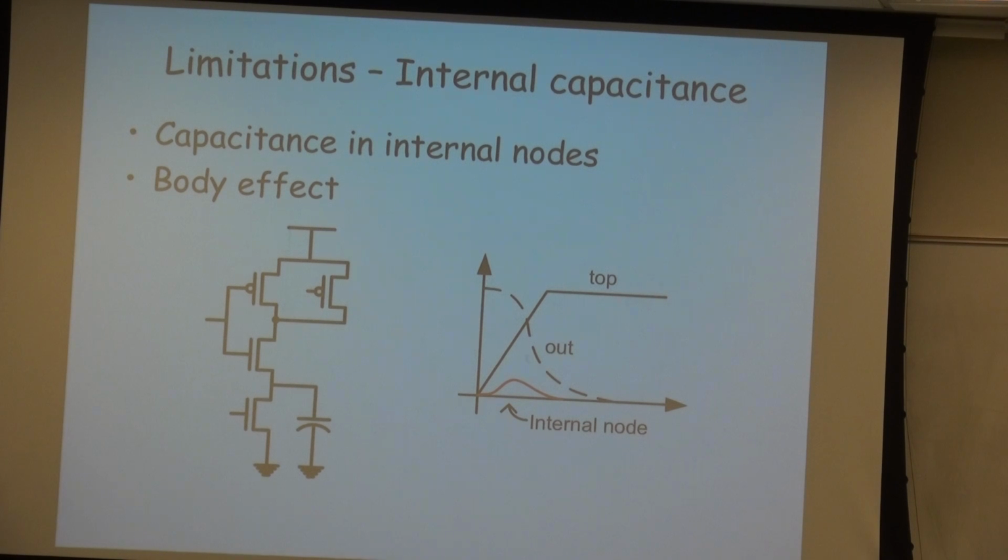What is the body effect? Who can say what the body effect is? Anybody? Do you know body effect? Yes. It's when the VT, or the threshold voltage, changes because of the body to source voltage. If the source is not at the same voltage as the bulk, then the threshold voltage will increase. Correct? We'll talk about that more later when we talk about low power circuit design. But that's what it is actually.